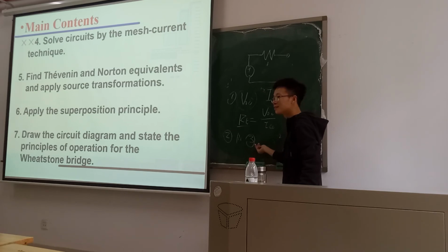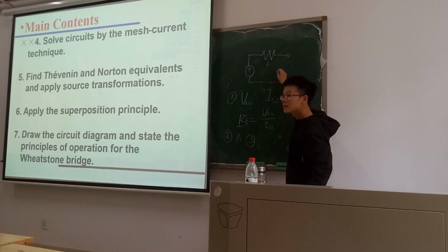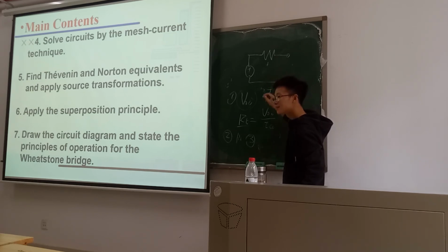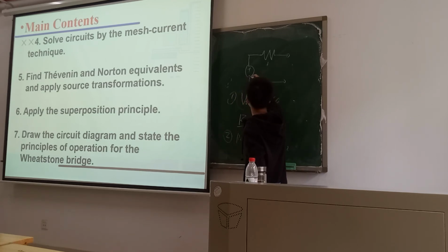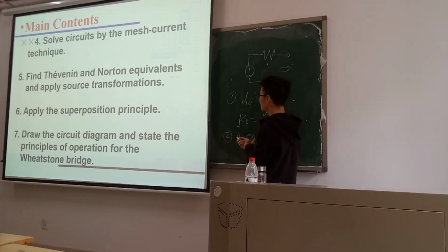The third method to get the Thevenin equivalent, okay? Source transformation. Right? We can use the source transformation to solve every circuit. I transfer this to the Norton's equivalent and we can combine the source and resistance together and then transfer the Norton's to the Thevenin and combine the whole circuit to this one or the Norton's form.